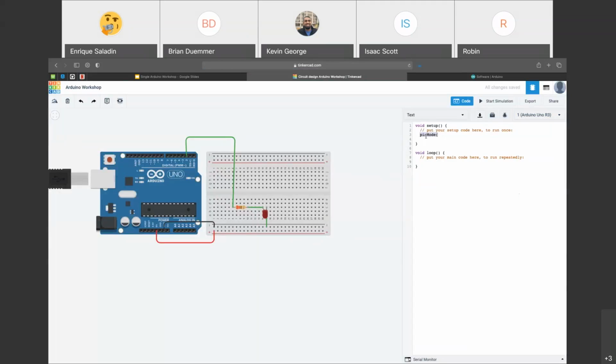So within every standard template, you're going to get 2 blocks of functions. This is a standard, so you're going to have a setup function and a looping function. So we use the setup function to declare our initial non-looping conditions like setting up what pin does what, or our variables, and so forth, you typically want to put under the setup function because those are going to initialize once and are not going to be continuous.